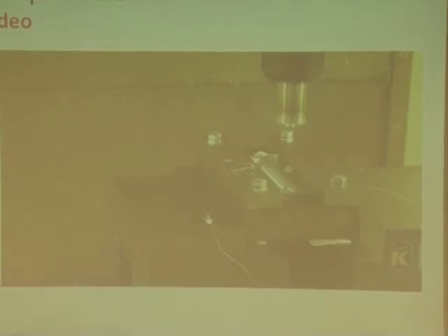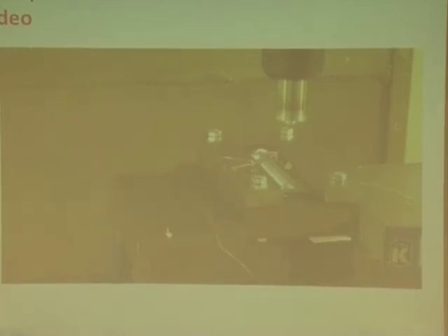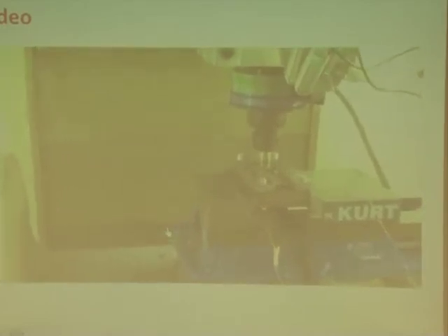Anyway, so there's a video that shows basically how it works, and it's almost like machining. It's like milling, almost like milling, except the tool does not cut. Again, the tool is spinning, and it's being fed in this direction. And this is all it takes. If you have the parameters correct, it looks very simple, but it's also very complicated. But if you know what you're doing, you have made, in fact, a solid-state weld.